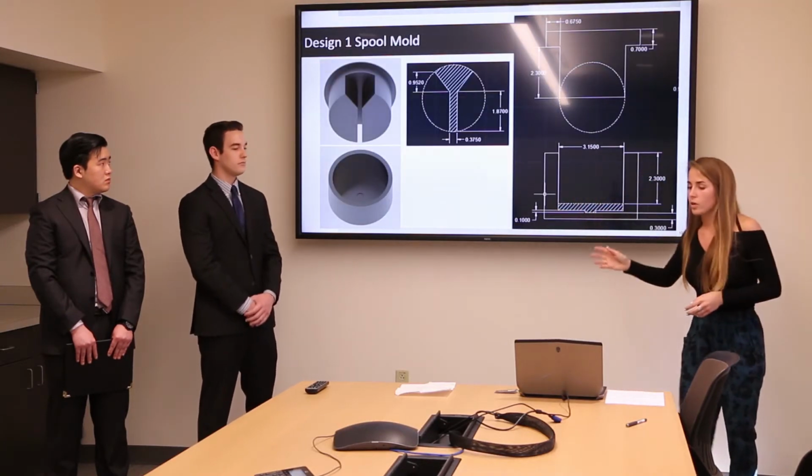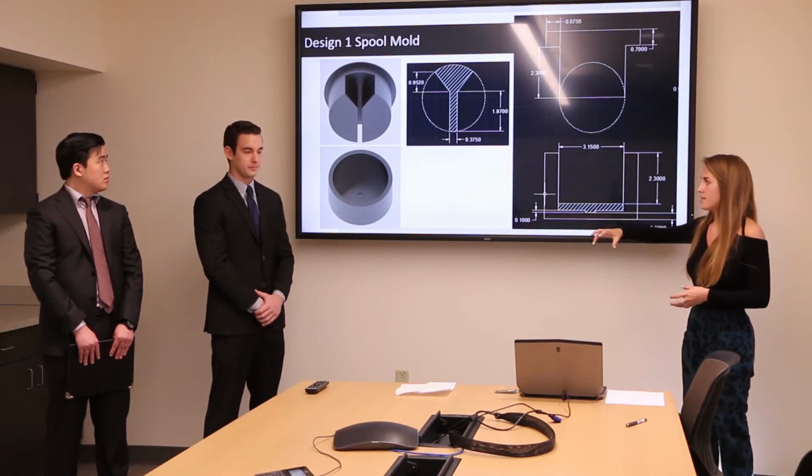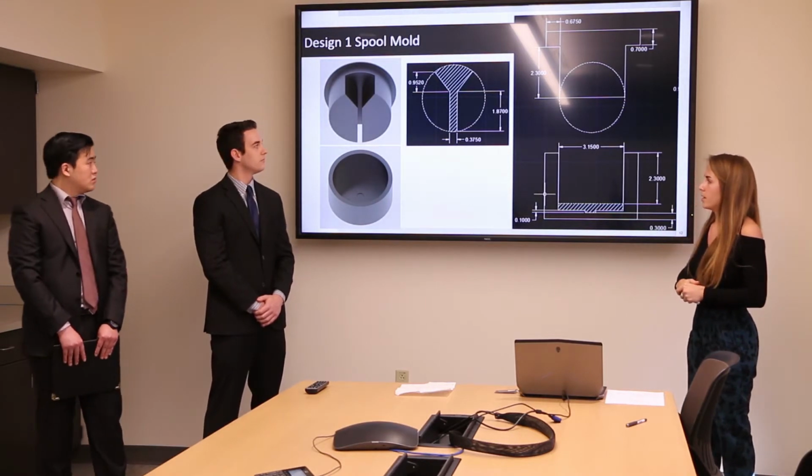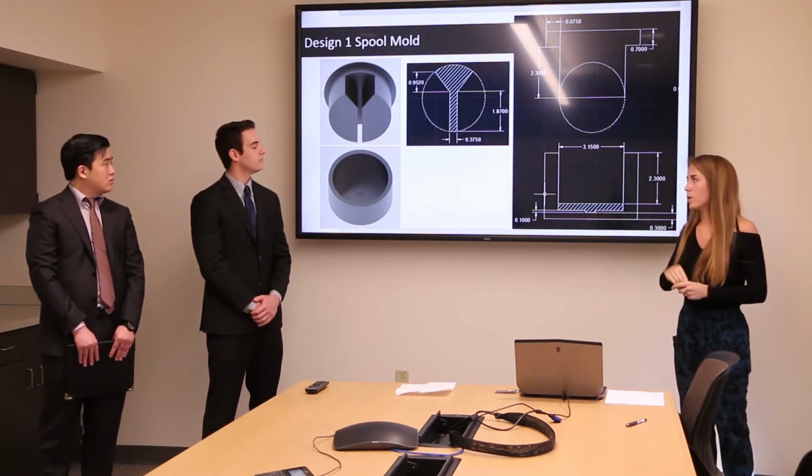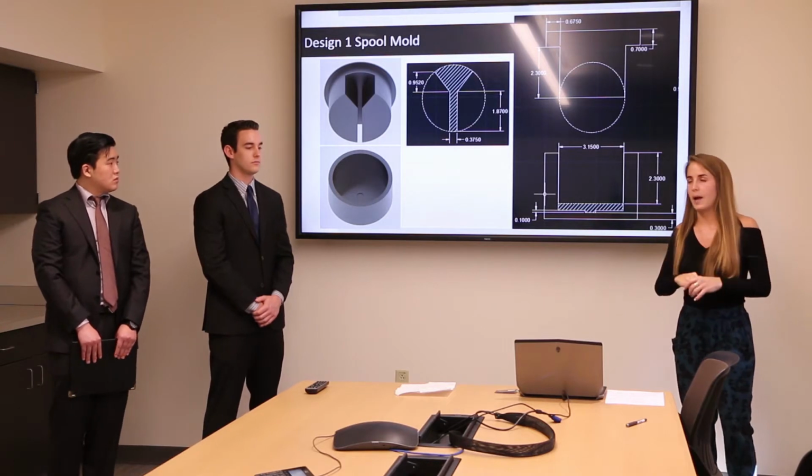So we designed the spool mold in a similar way. Side A comes down on top of side B. The injection material is inserted, and once it cools, the cam pins push that plastic up.